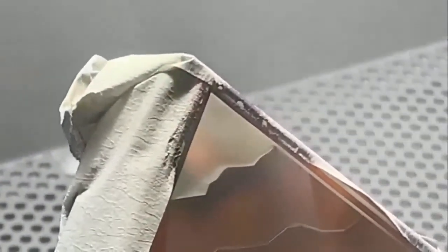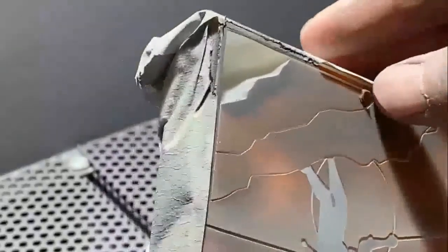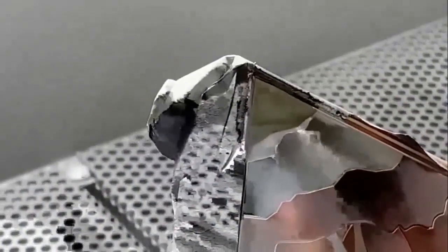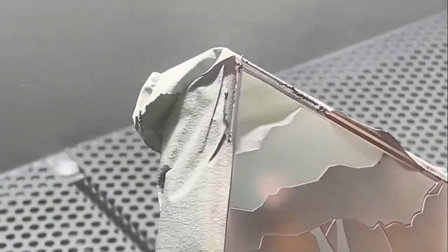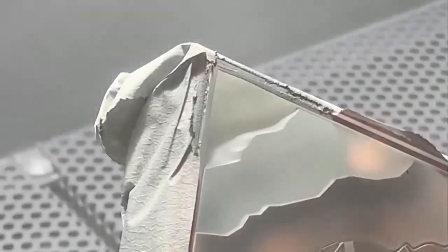And you're going to notice a light hitting there. It's not a flashlight on your nozzle like a lot of you may notice. It's actually the silicon carbide that's sparking on the glass, creating a flashlight effect. And that's only with silicon carbide. So the carbide abrasive is very important because it gives you that spark, so you know you're blasting at all times. You're not wasting time in the machine trying to find out what needs to etch, what needs to go deeper, and whatnot. So carbide really makes your job a lot easier, but also more fun.